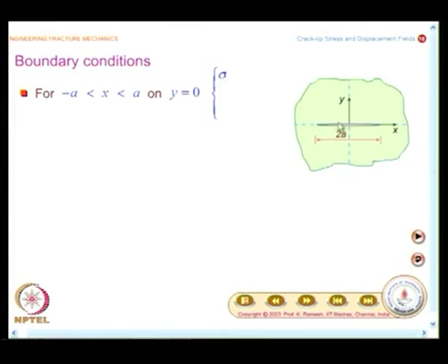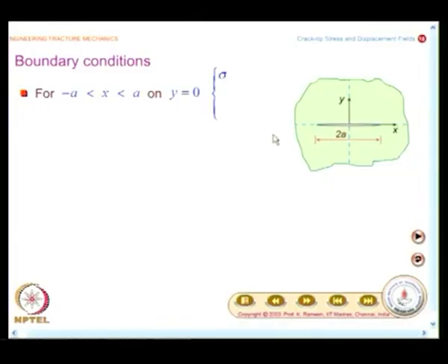That is very, very important. I have this as a free surface, shear cannot cross a free surface, so shear stress can be 0, that one condition I can write. Between sigma x and sigma y, which stress component should go to 0? Sigma y. So, if you recognize that, then the first boundary condition is completely specified.